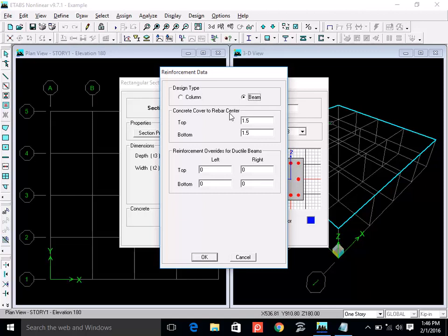This is actually in eighths of an inch. For number 3 the diameter is 3/8 inch. The diameter is 4/8 inch, 5/8 inch, 6/8 inch, 7/8 inch, and 8/8 inch, which is of course 1 inch. This is 1 inch, and this is half inch.